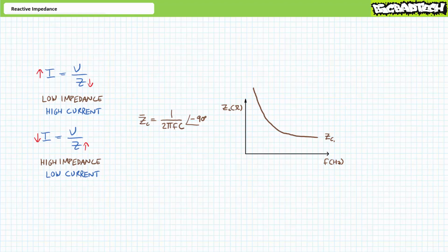Conversely, at high frequencies, quickly oscillating waveforms present rapidly changing voltage. As a result, the capacitor has a high incentive to rapidly charge or discharge, resulting in massive exchanges of current, i.e. current is high at high frequencies, synonymous with a low impedance element. If you think about it, capacitors in high-frequency systems are always in the early stages of a charge or a discharge, synonymous with a high burst of current.